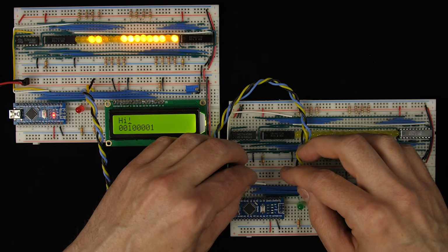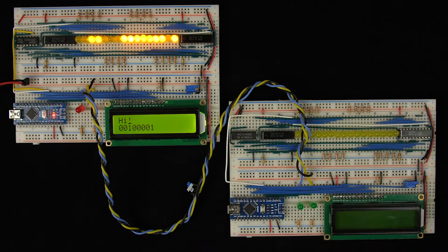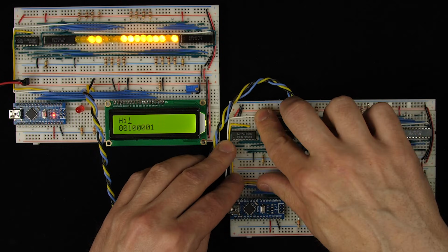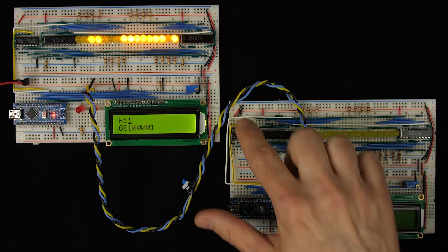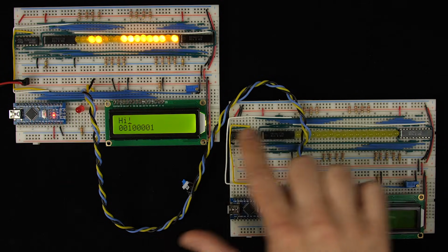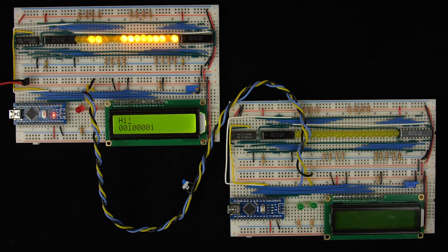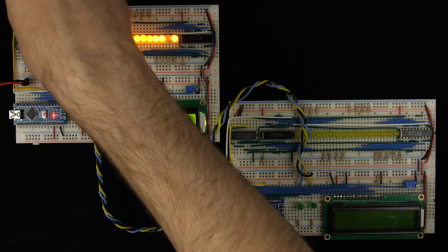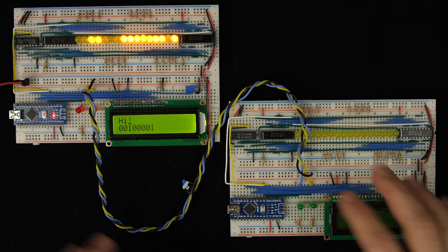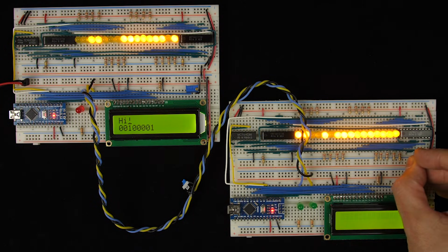And then I'll hook up the clock and data to a receiver. And actually, I just noticed one thing that I didn't do over here is I have the unused inputs for the 1 XOR gate that I'm not using. I just have those tied to ground. So let me do that on this one here too. Okay, now let's power up the receiver with the CRC circuit.